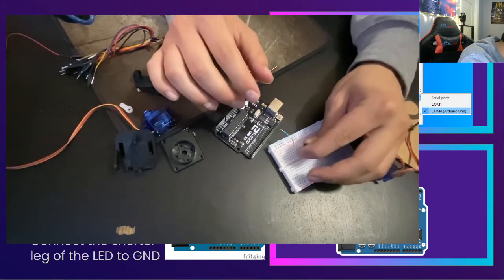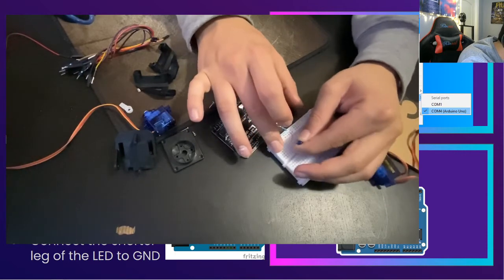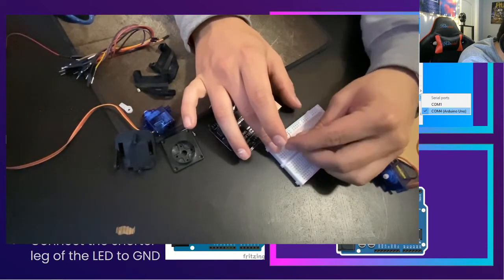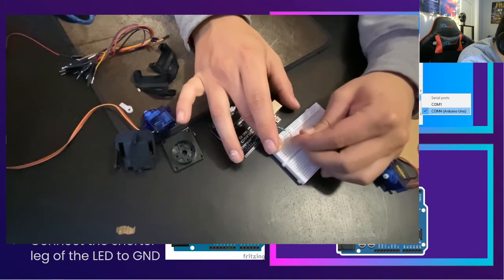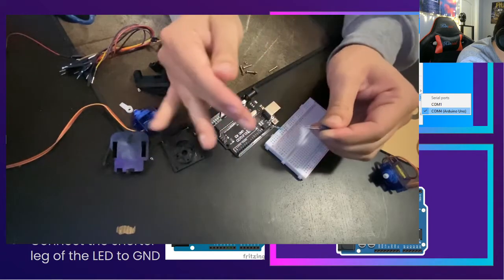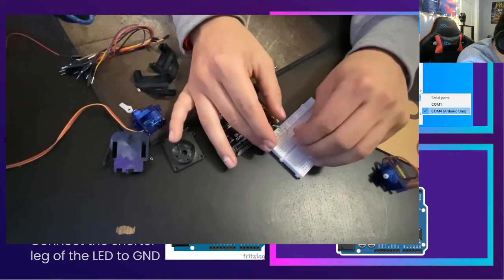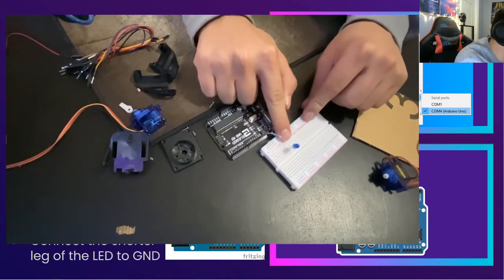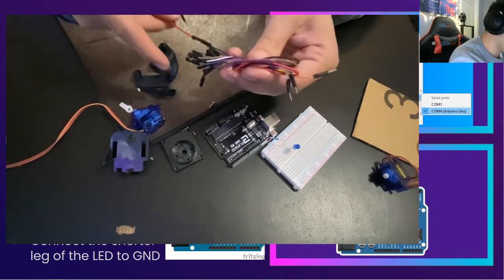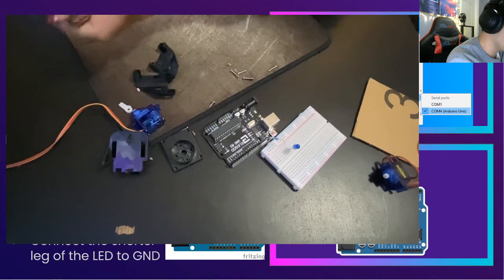But from there we're gonna connect the long end of the LED to the other side of the resistor, and then let me make sure these are, so we're gonna do that. We're gonna put the long side of the LED to the resistor, and then if you have a wire, go ahead and get a female to female wire.